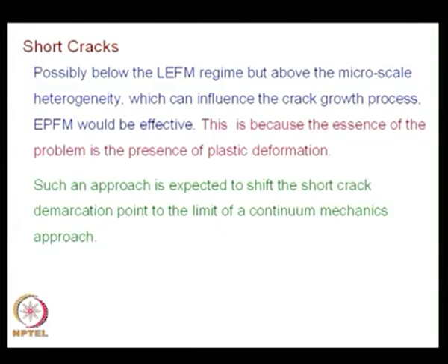So, from LEFM, if you go to EPFM analysis, you could analyze still smaller cracks, but it does not start from 0. Then you have this micro scale heterogeneity and so on. So, the use of EPFM is expected to shift the short crack demarcation point to the limit of a continuum mechanics approach.